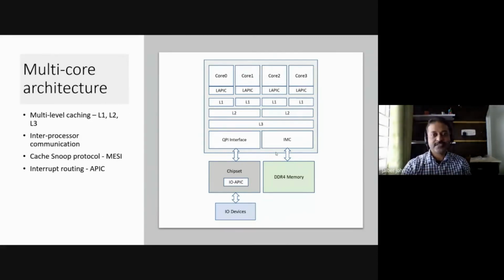And this L1 cache, what I show here, also consists of 2 caches, the instruction cache and data cache. I told you that each instruction is broken down into multiple micro ops, right? So let's say we have an instruction which the decoder has decoded into multiple micro ops. Now, what do we do with that? Should we throw it away?